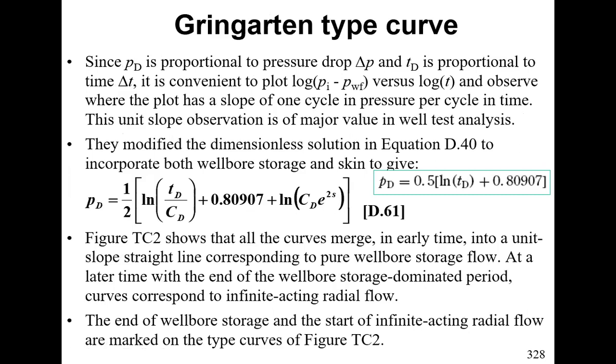Now, since the dimensionless pressure is proportional to the pressure drop and the dimensionless time is proportional to the shut-in time or the flowing time, depending on the nature of the test, it's convenient to plot the log of the pressure difference versus the log of time and observe where the plot has a slope of 1.